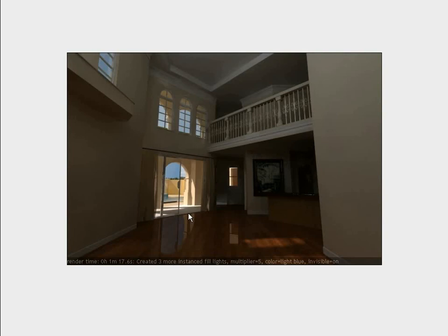But after I create the first light, I should only have to worry about assigning an intensity value relative to that first light. The fact that the fill light is larger means, of course, that more illumination will be projected than if the fill light were smaller, but I just need to assign a relative intensity value right now. And I can come back later if I decide that the overall total illumination is not correct after I fill all the openings with lights. But right now I'm just trying to assign a proper intensity value relative to that first light that I created with an intensity value of 10.